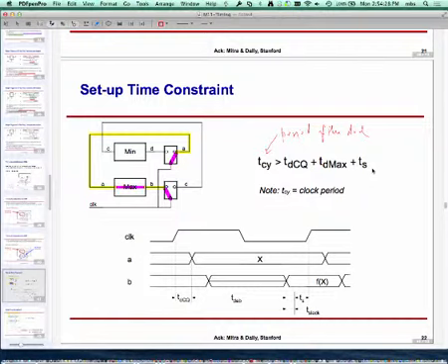The reason is that when your chip comes back, if you look at the flip-flops and you measure their TDCQ, they're going to be different. So it will actually be some sort of a probability distribution, usually looking like a Gaussian curve. There will be an average, some spread around it, and then you are going to pick a value for which you will say, 99.99% of my flip-flops have a delay less than that.